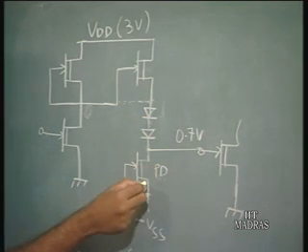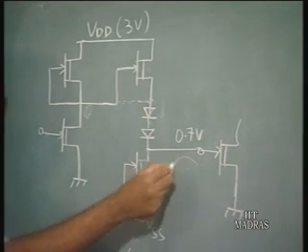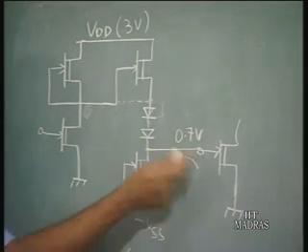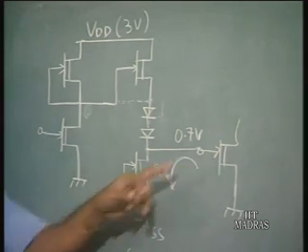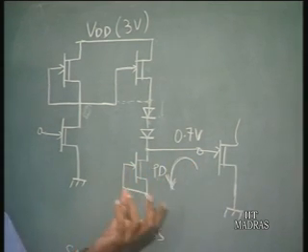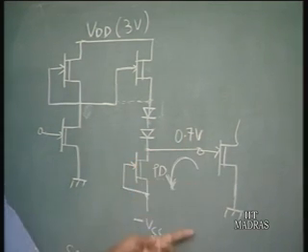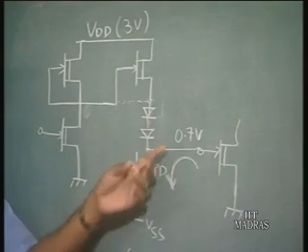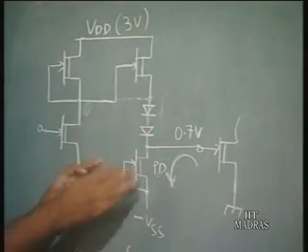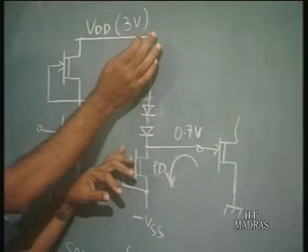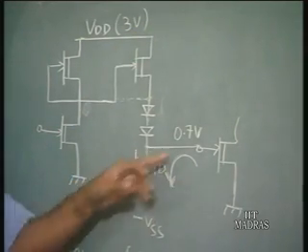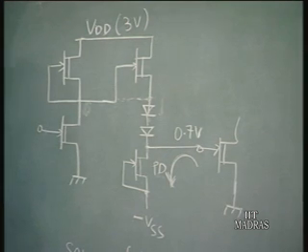This pull down transistor is of course on, so a current flows out of the input of this output transistor and discharges its input capacitance, so the output voltage is going to fall. So here there is no clash of currents. The pull down transistor is on, the source follower is off, and the full current of the pull down is used to switch off the output transistor.